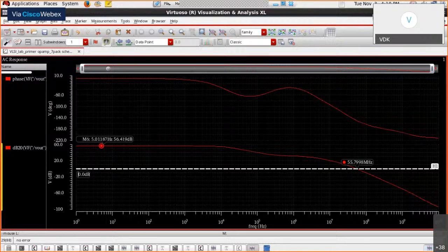So we started with setting the perspective for analog, also giving the application perspective in the morning. Then in the first session, we developed and evolved the circuit topologies for various amplifiers, starting from the basic gain stage, then modifying that to a common source amplifier with resistive load, then to the common source amplifier with a PMOS type source load.